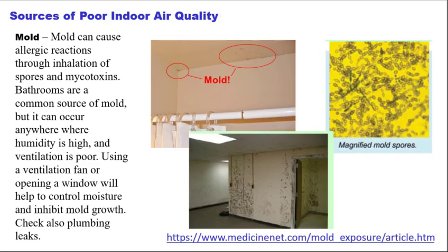Mold can cause allergic reactions through inhalation of spores and mycotoxins. Bathrooms are a common source of mold, but it can occur anywhere where humidity is high and ventilation is poor. Using a ventilation fan or opening a window will help to control moisture and inhibit mold growth. Check also for plumbing leaks.